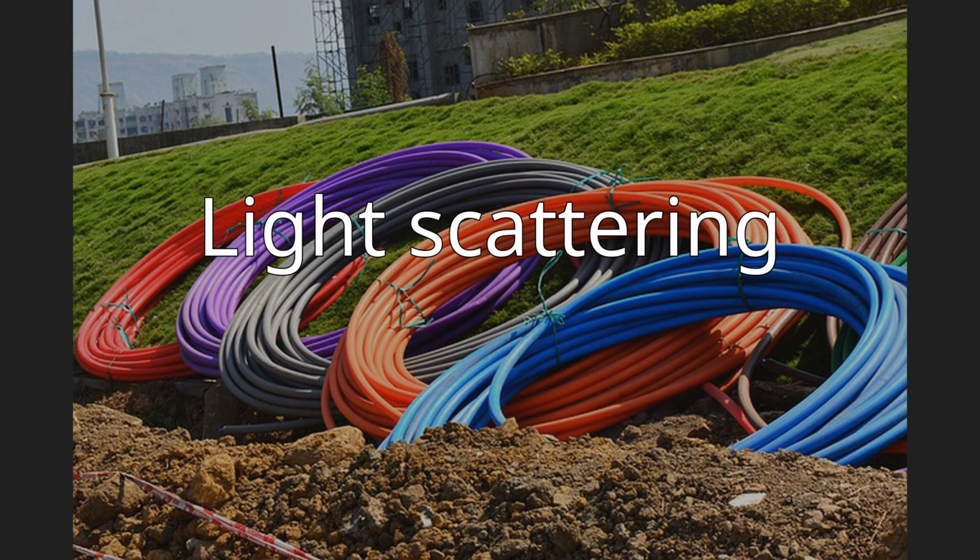Similarly, the scattering of light in optical quality glass fiber is caused by molecular level irregularities, compositional fluctuations in the glass structure. Indeed, one emerging school of thought is that a glass is simply the limiting case of a polycrystalline solid. Within this framework, domains exhibiting various degrees of short-range order become the building blocks of both metals and alloys, as well as glasses and ceramics.